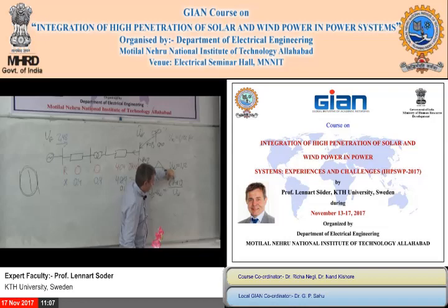So here you have an increase, here you have a decrease, because Q is going in the other direction. The question is, how much does that decrease the voltage? It depends on the size of the X. Now X is decreasing because you change to a cable. So when you change to a cable, the impact from the reduction is decreasing.